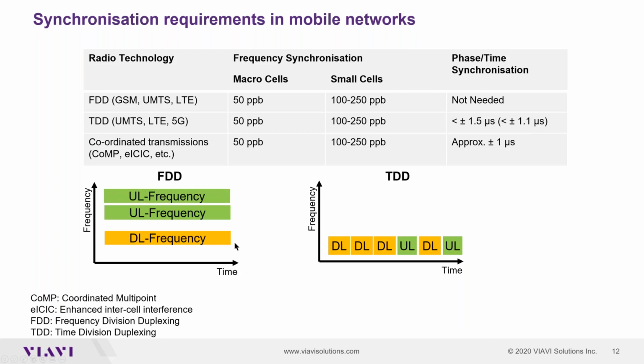And it's organized in this way that if there is another mobile, it has another uplink frequency and another downlink frequency. And all uplink frequencies are organized in the same frequency band, and the downlink also in the same frequency band. And in between, you have a guard band to make it really secure that there is no interference between these frequencies. You always need to know, when you're here with the mobile, uplink, you have a strong signal. Downlink, you have a weak signal, and therefore a strong signal can interfere with the weak signal. But if it's that well separated, no problem.